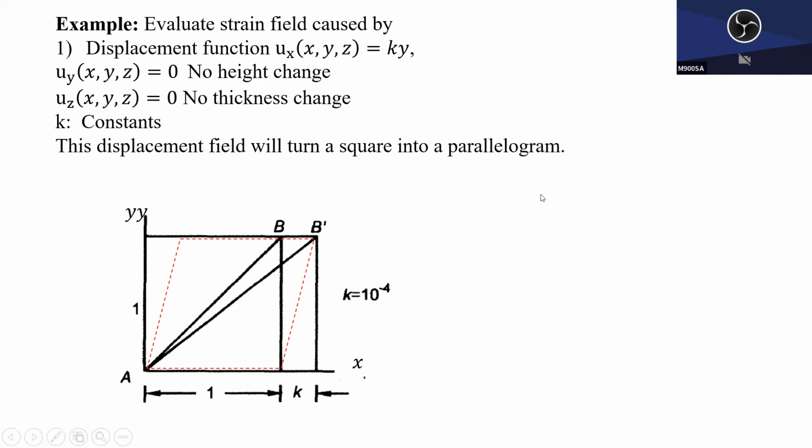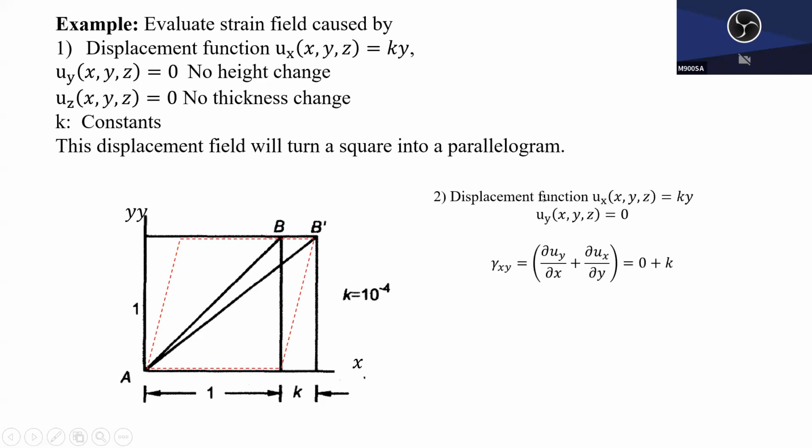So using this displacement field, we apply this differential equation here, and then we can find out that the shear strain of this rectangle twisted into a parallelogram is k. Good.